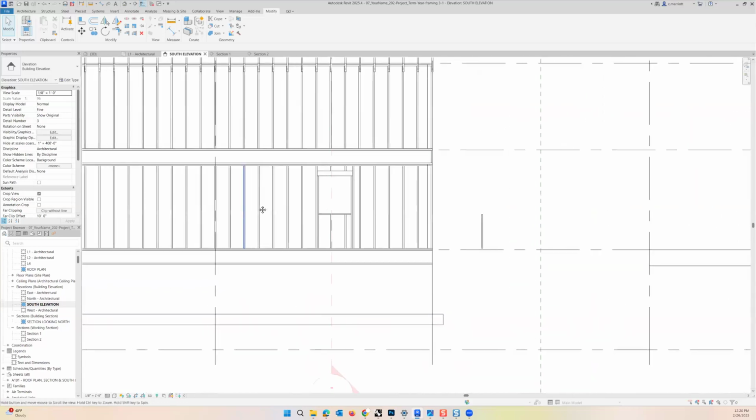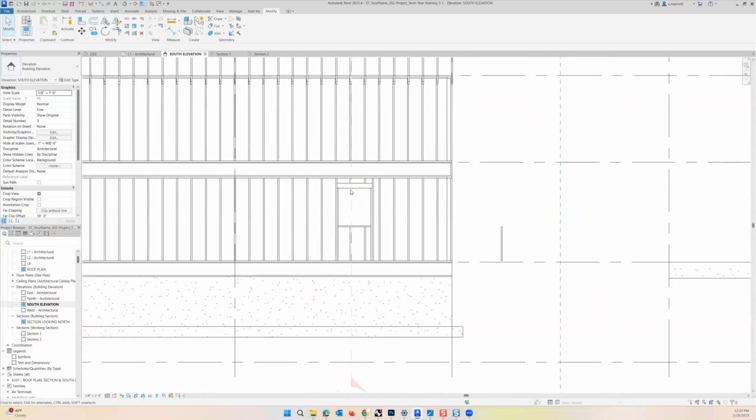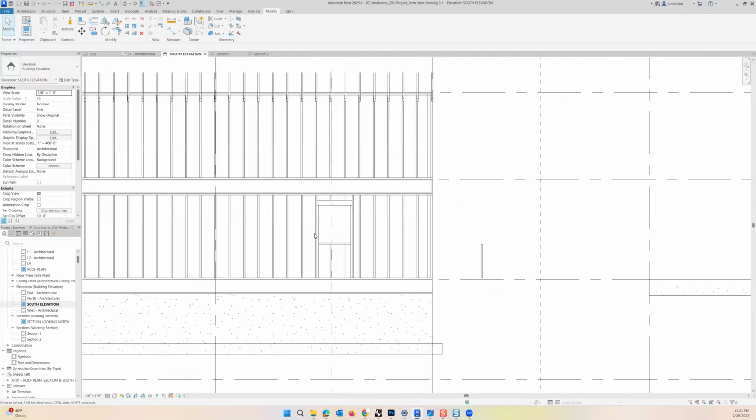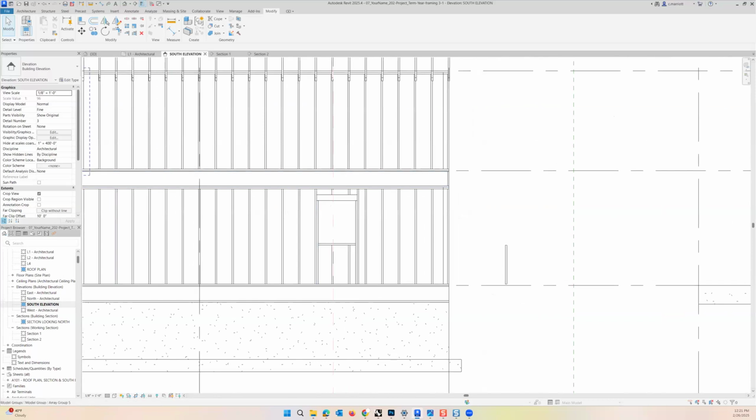All right, so to create another one of these windows, if you're using a narrow one, you could create a new header, or you should create a new header that's only 3.5 inches tall. It would be made up of 2x4s. Maybe you want to keep the same head height for that window. Maybe you want to modify that. But the process would be the same: determining what the rough opening is, both in width and in height, and then adding all of these additional members to frame out the rough opening. That's it for this part.